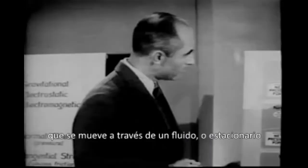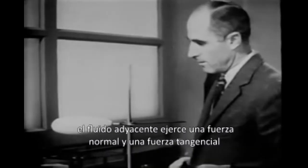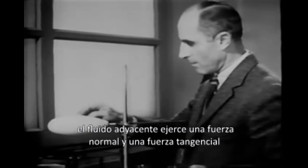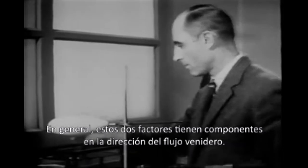We've talked a great deal about the forces and the motions and how they are related for typical fluid particles. But now how about the forces acting on an object, moving through a fluid or stationary in a moving stream of fluid? The important idea here is that these forces are exerted on the surface of the object by those fluid particles which are in immediate contact with the surface. On every element of surface area, the adjacent fluid particle exerts a normal force and a tangential force. In general, these two forces have components in the direction of the oncoming flow.